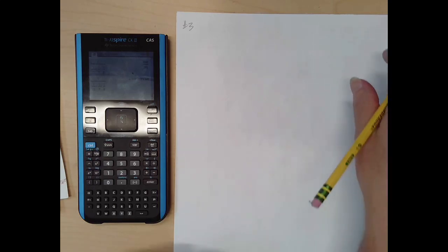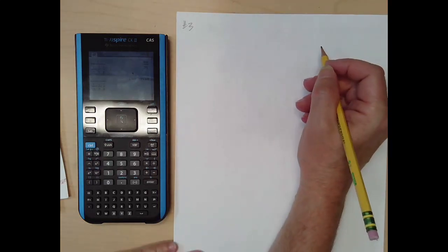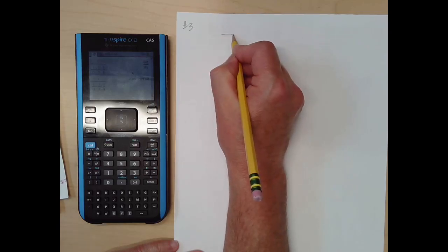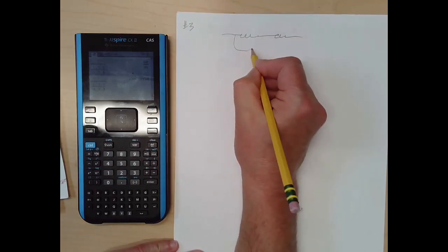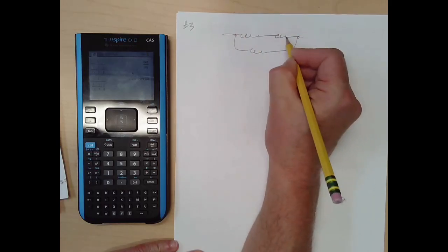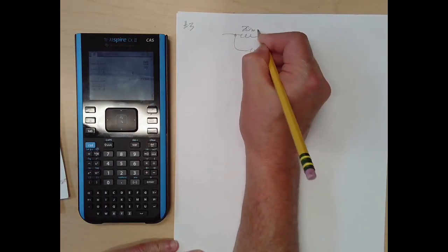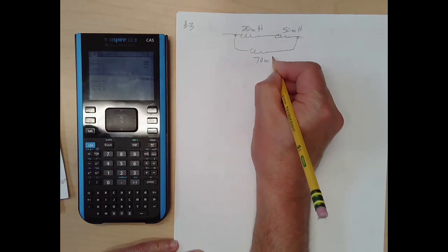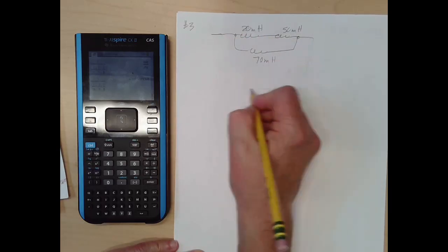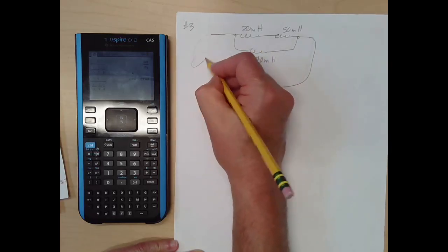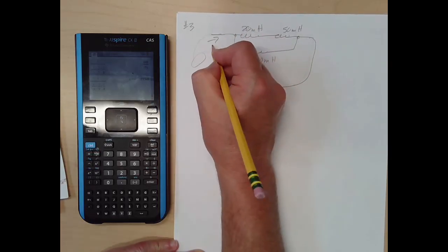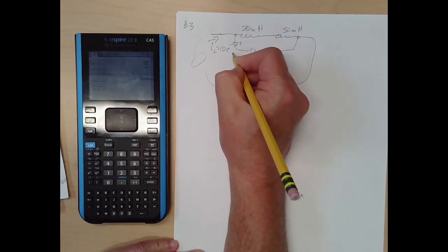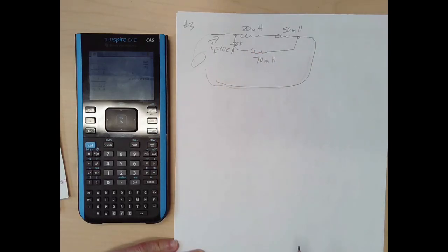Okay, let's look at an inductor problem now that's got this time dependence in it. Let's say we have 2 inductors in series. Bad writing here, but 20 millihenries, 50 millihenries. I'm going to say this one's 70 millihenries. And we know we got some sort of a closed loop, some sort of a source over here, and we know the current through the inductors is 10 e to the negative 50t amps. Kind of getting messy here, but hopefully you can see that.